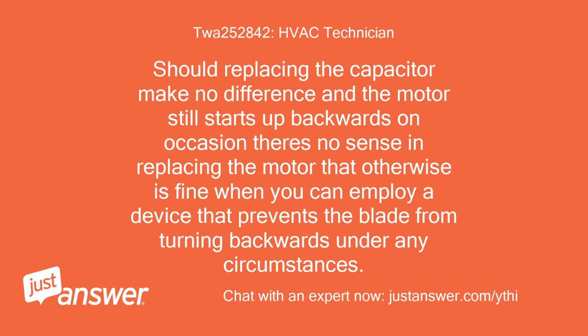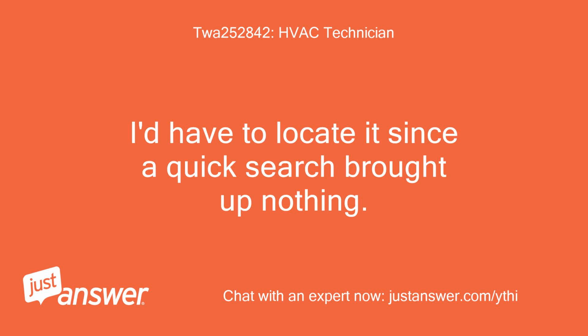Should replacing the capacitor make no difference and the motor still starts up backwards on occasion, there is no sense in replacing the motor that otherwise is fine when you can employ a device that prevents the blade from turning backwards under any circumstances. I'd have to locate it since a quick search brought up nothing.